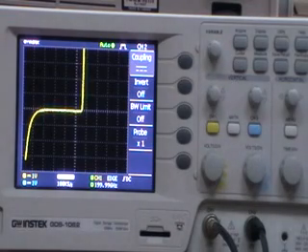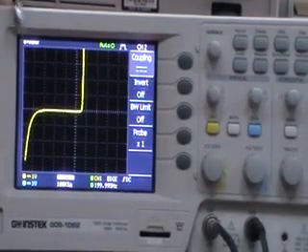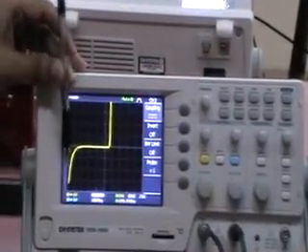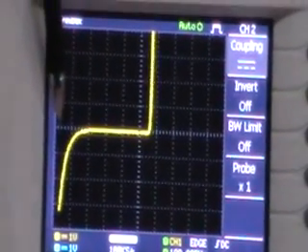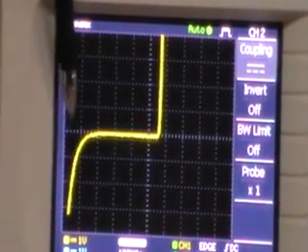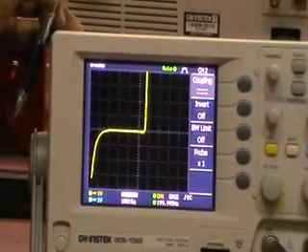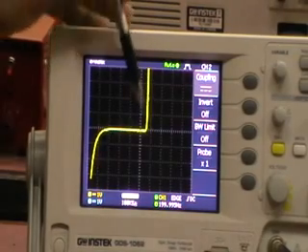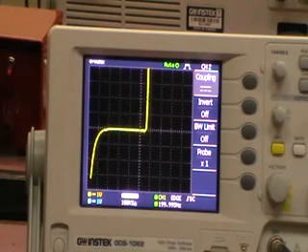As you can see, the Zener breakdown voltage is shown in the diagram in the manual, that is the peak inverse voltage. We have to draw a linear tangent line along the slope line, and that voltage point on the x-axis, with voltage on the x-axis and current on the y-axis, will tell us the Zener breakdown voltage. Similarly, to find the forward knee voltage as said in the previous case, draw a tangent along the forward characteristics, and the point where it touches the x-axis will give the forward knee voltage. So by doing this, the Zener part is completed.